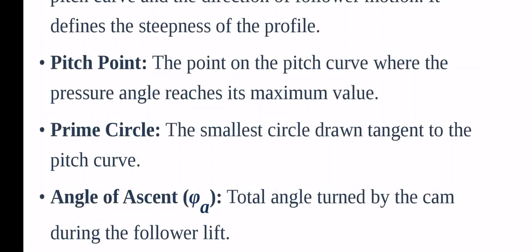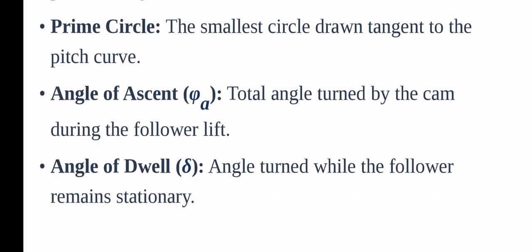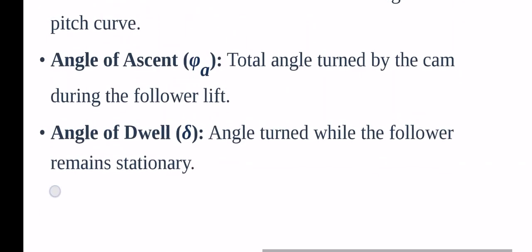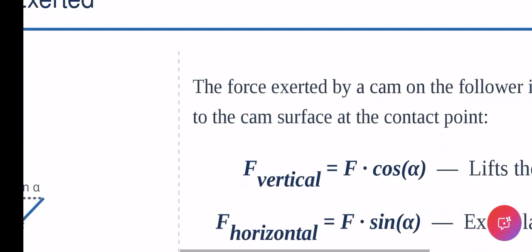Prime circle: the smallest circle drawn tangent to the pitch curve. Angle of ascent: total angle turned by the cam during the follower lift. Angle of dwell: angle turned while the follower remains stationary.